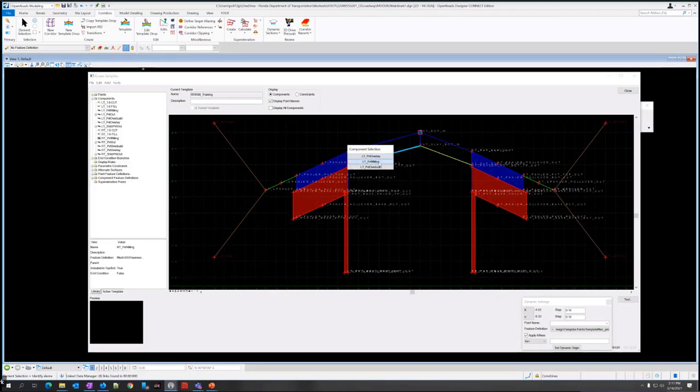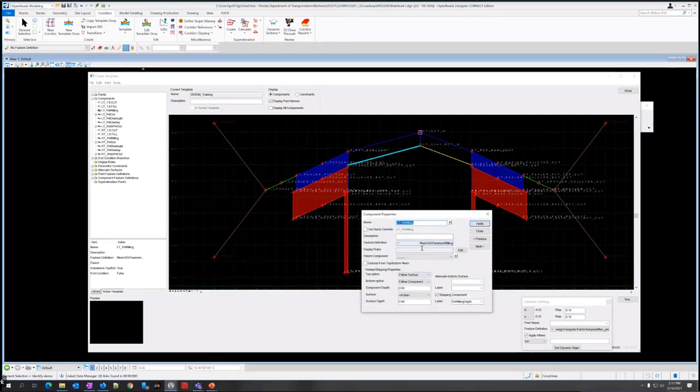So I'm going to edit the left one too. Double click on this and select the middle one. So it's LT PVT milling. Just make sure it looks right. So the top is following surface, bottom is following component, surface is active. Looks good.